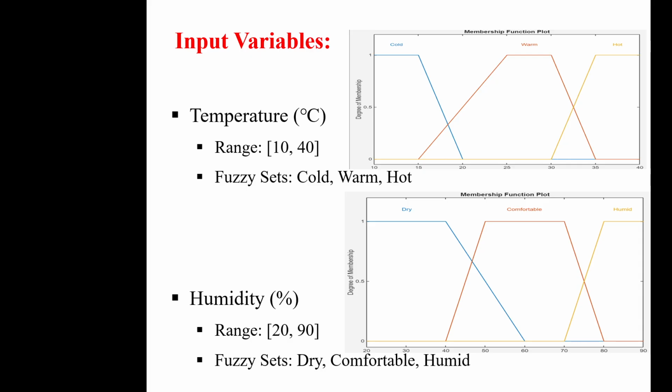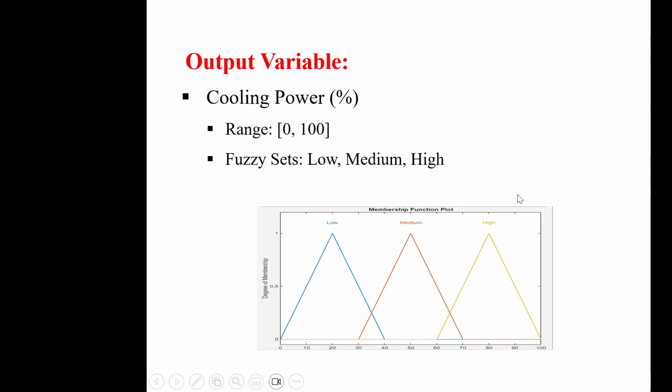This is the defuzzifier, because the fuzzy value that we are going to get from the inference engine cannot work on the plant, and therefore the defuzzifier will now try to convert the fuzzy value back to a physical value. The physical value that we now obtain will work on the plant, so as to make sure that the necessary parameters that we expect from the plant we will be able to achieve.